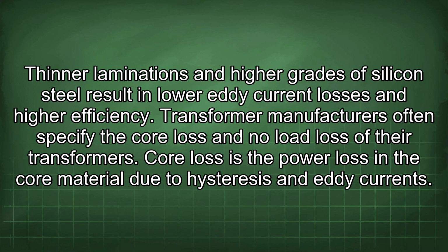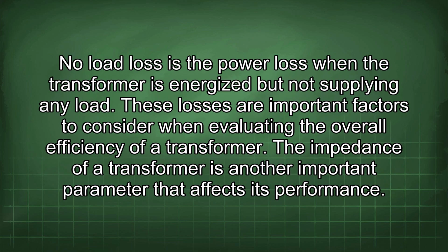Transformer manufacturers often specify the core loss and no-load loss of their transformers. Core loss is the power loss in the core material due to hysteresis and eddy currents. No-load loss is the power loss when the transformer is energized but not supplying any load. These losses are important factors to consider when evaluating the overall efficiency of a transformer.